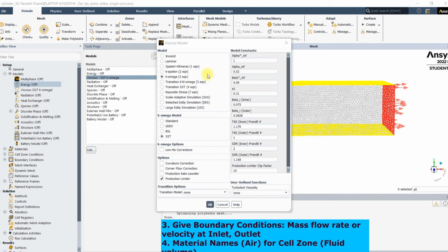There is also the LES model, but it is solved only for transient. Here for the RANS model, please note that it solves only time average equations. Each model has some basic models, and you have to note them. There are also some other modifications, like low Reynolds number correction.